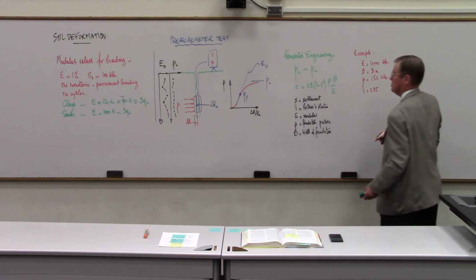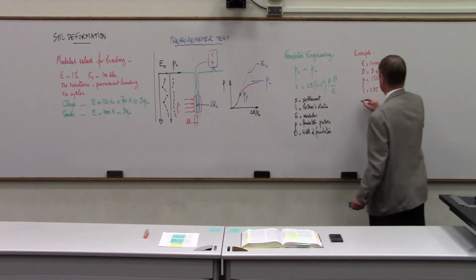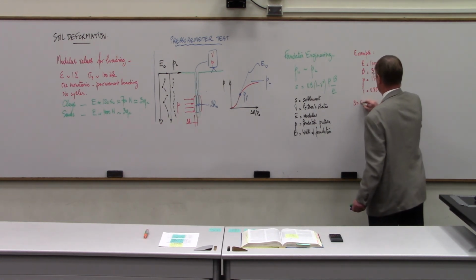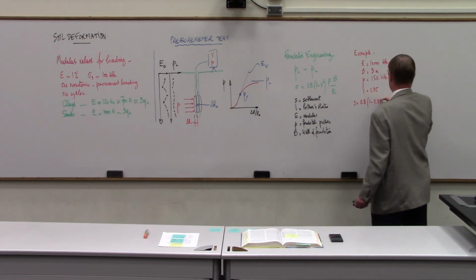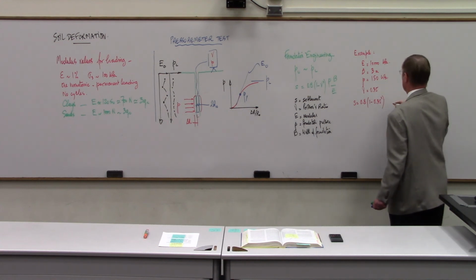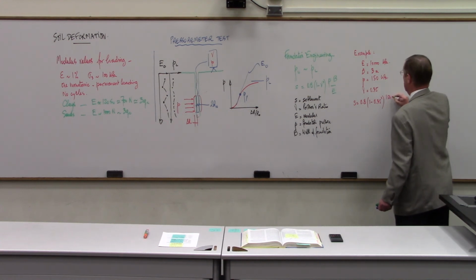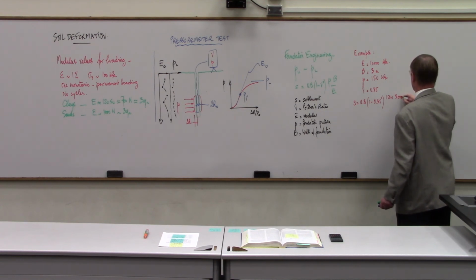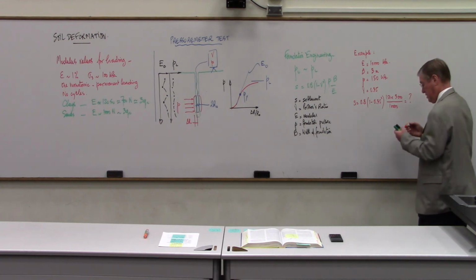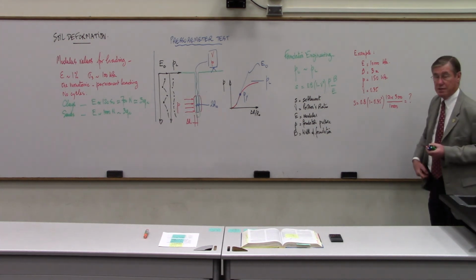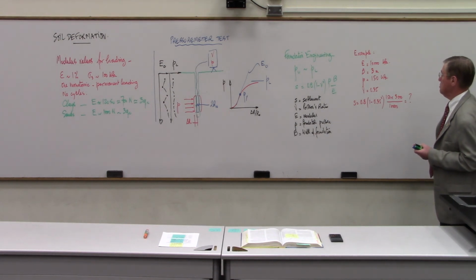This number here is a shape factor, so then we would get S equal 0.8 times (1 minus 0.35 squared) times 150 times 3 meters. And if we want the results in millimeters, I'll put 3,000 here, and then divided by the modulus 10,000 kilopascal. So I don't know what that is, but that's how we would calculate the settlement.